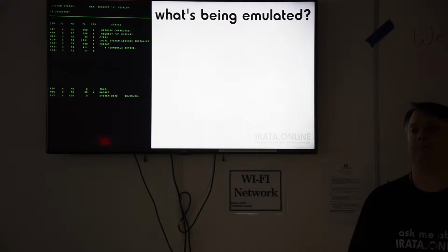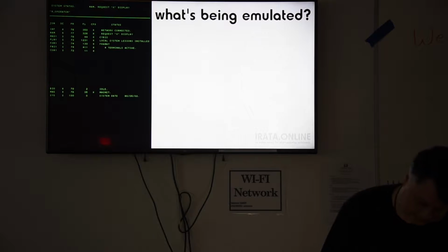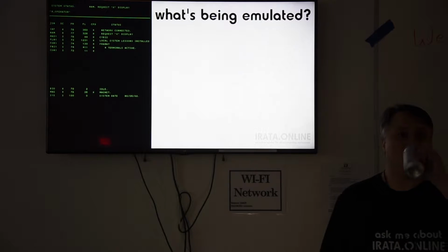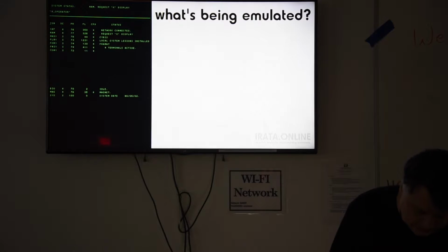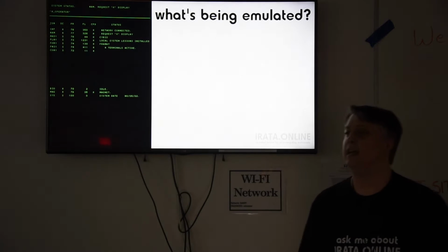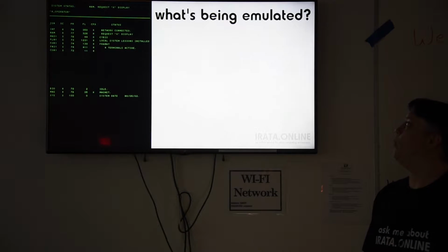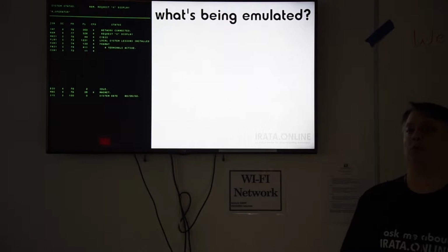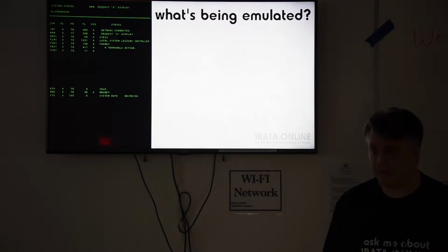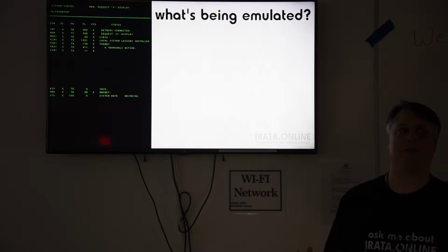It's a 60-bit machine, that's 60. The registers and the memory are that size. And the machine itself has approximately 1 megaword of extended core storage, which is used as the swap, and approximately 1 megaword of central processor memory, into which the entire program is actually running.